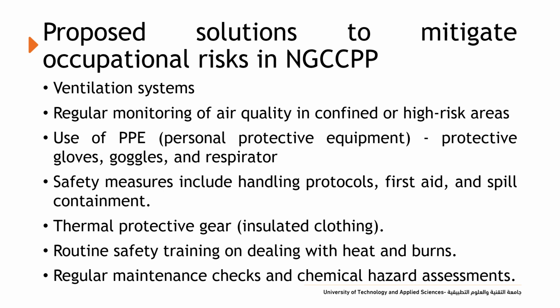The safety measures include handling protocols of various materials and machines, and first aid precautions and spill containment should be notified to all the manpower of the industry. Thermal protective gear such as insulated clothing is very important at appropriate places. Routine safety training on dealing with heat and burns should be provided to the manpower once in 3 months.